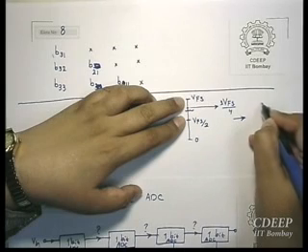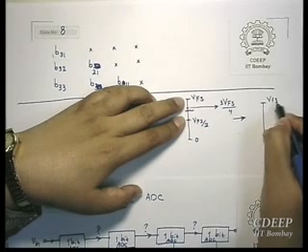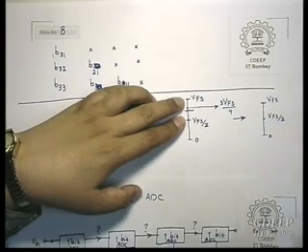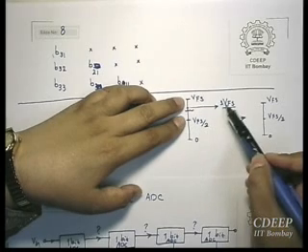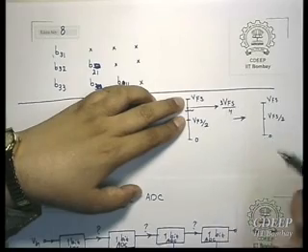If I again keep the scale for the ADC the same as before, I have a 1 bit ADC, I cannot change my reference value. But what I can do is deduct V full scale by 2 from the signal.